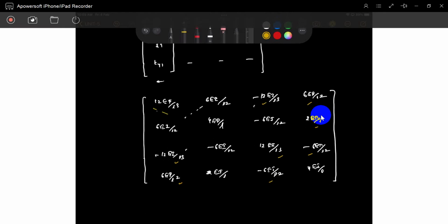So diagonal elements, if you observe diagonal elements, everything is positive, because what is a diagonal element? K11, K22, K33, K44. The force generated in the direction of the 1, when the deformation is only in the direction of 1, or II, JJ type. So if you apply a force in a direction, the deformation should be in the direction of the force only. There is no chance of the opposite direction. So that's why everything is positive, but the remaining may be opposite. Forces may be generated in the opposite direction. So the remaining quantities may be positive or negative, but the diagonal element should be positive.